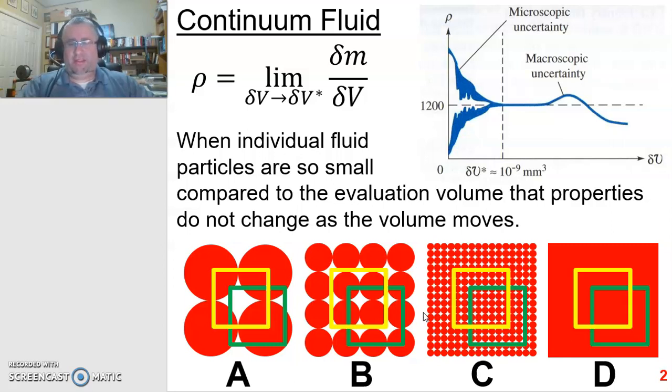And if I try to calculate the density, given that those boxes are the same volume, I'm going to get 2 different densities just depending on where I'm looking in the fluid, right? So still, I can't assume that this is a continuum fluid because I'm still seeing the individual influence of the particles and the spacing between them.